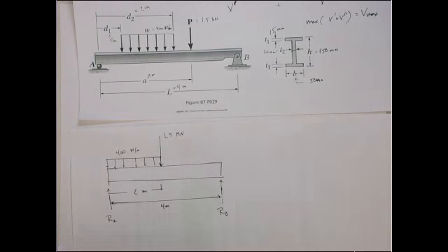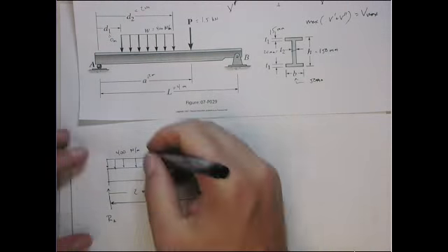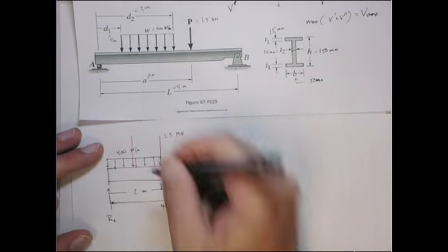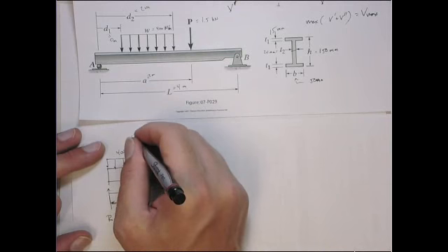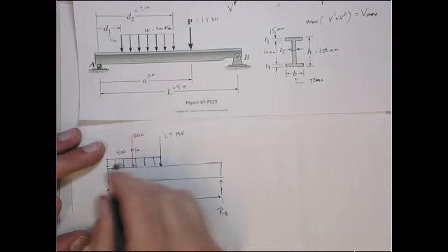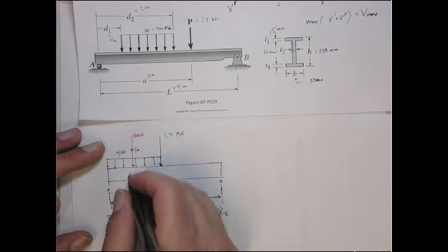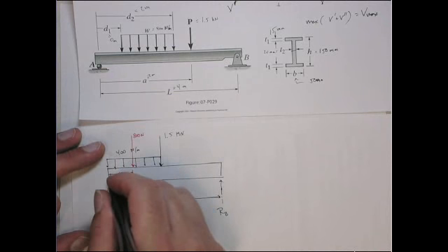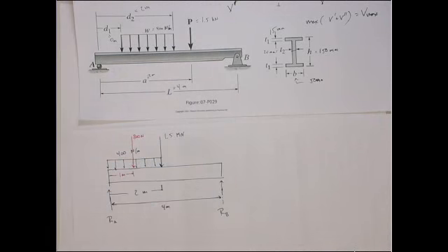So this one has an effective down force of 800 newtons. That's the 400 newtons per meter over 2 meters, and its location is 1 meter from the edge. So we can treat it like this to do the equilibrium for the whole body, to get the reaction forces.